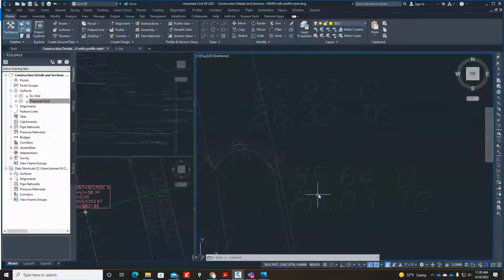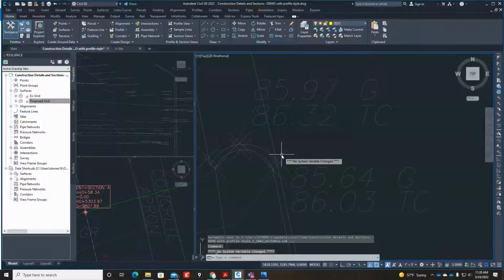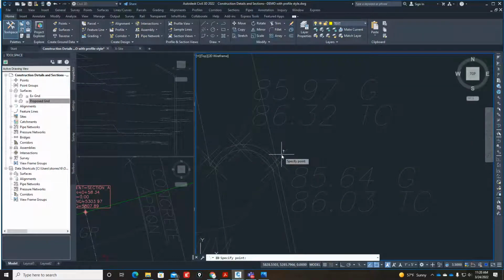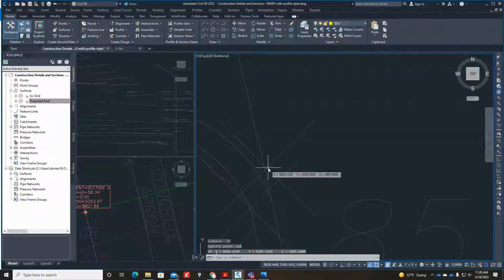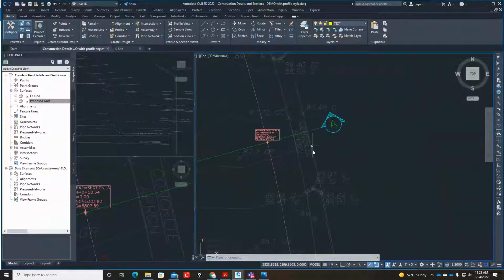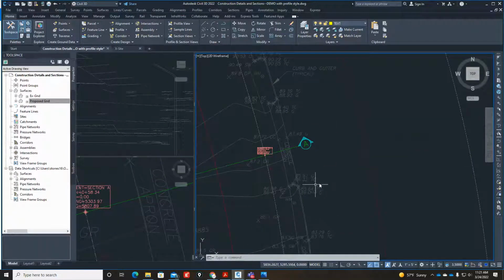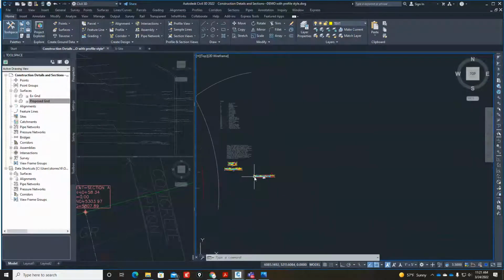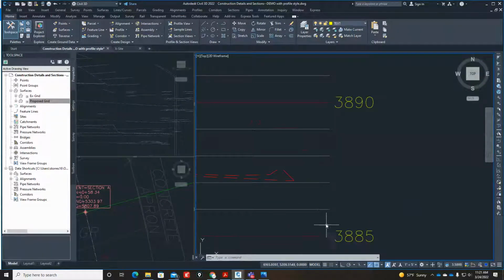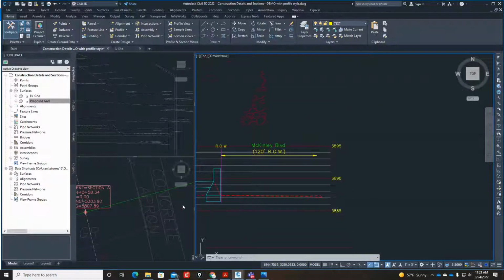If you don't know what that is, you can ID the node point. That guy right there, and that's your, did I grab the right one? Node. Yeah. That's your 8564, which is that gutter right there. So just by looking at it, 8564, 87 should be like 87 something. So let's go back over here, see what we got. 85, 86, 87. Okay. I think I can go with that. So I can safely call that one the gutter line right there. So I can call that the gutter.